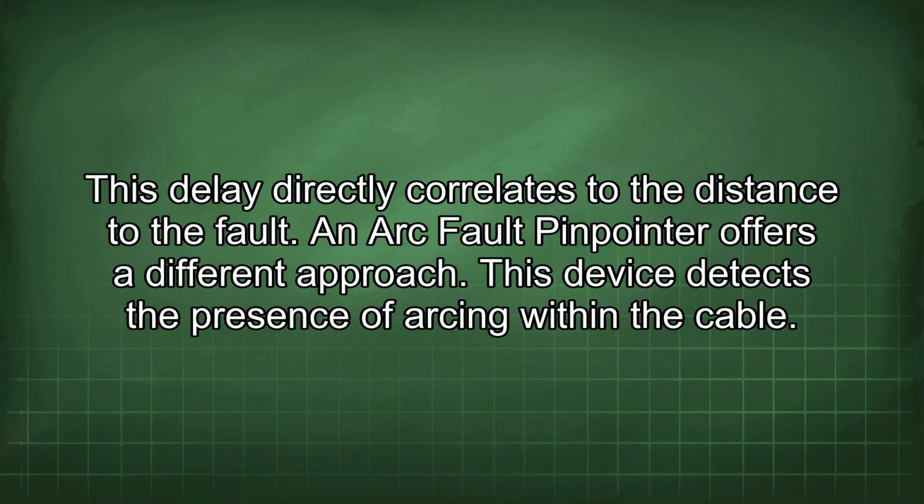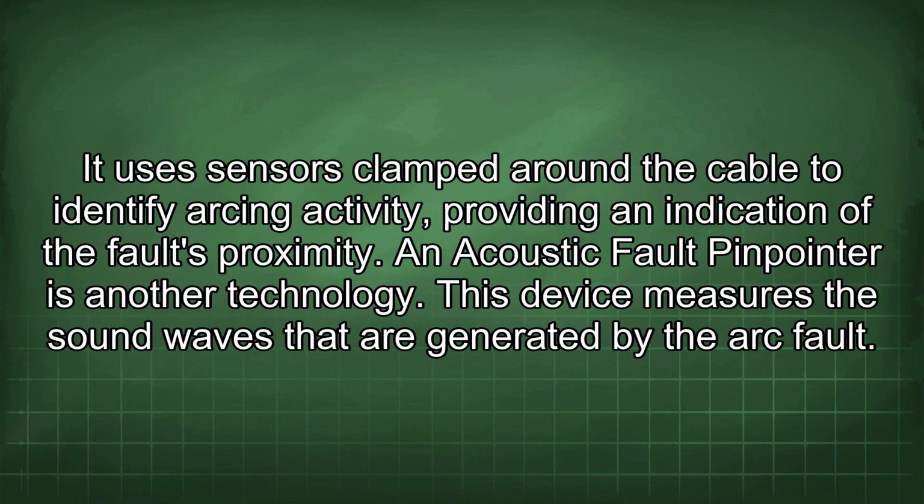An arc fault pinpointer offers a different approach. This device detects the presence of arcing within the cable. It uses sensors clamped around the cable to identify arcing activity, providing an indication of the fault's proximity.